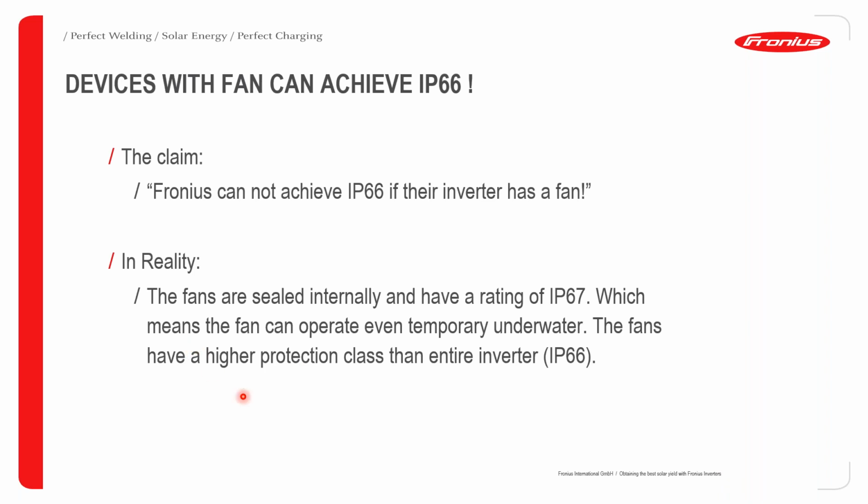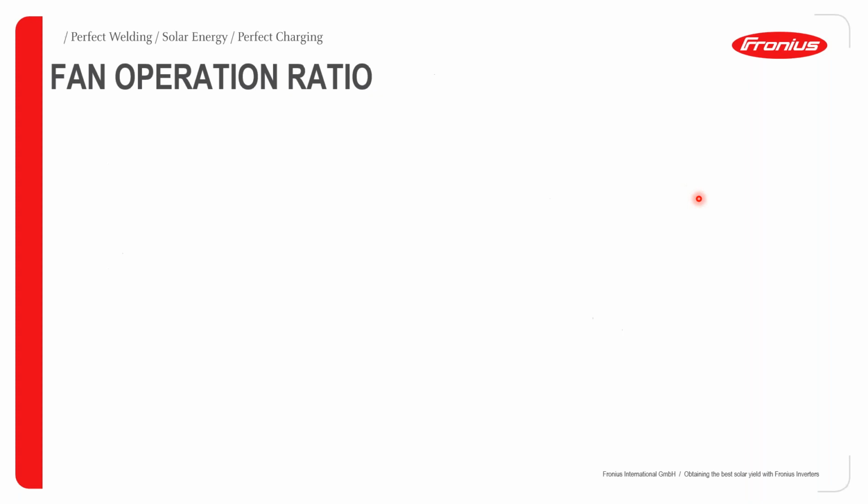But in reality, the fans are sealed internally and have an IP67 rating, which means that these fans can actually operate even temporarily underwater. And in general, the way the fans are constructed, they even have a higher IP rating than the entire inverter. So the inverters will mostly attain IP66, but the fans can actually go a step further and achieve IP67.